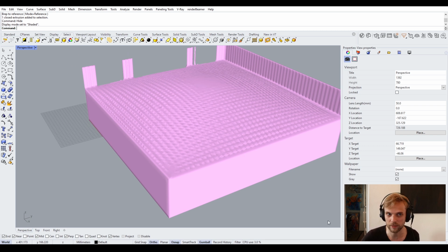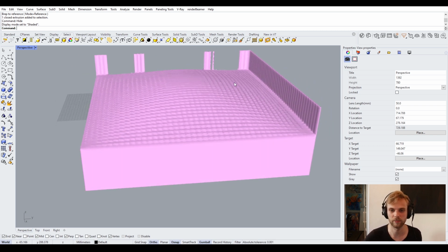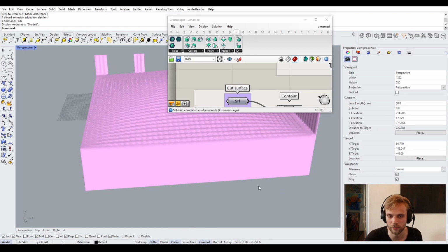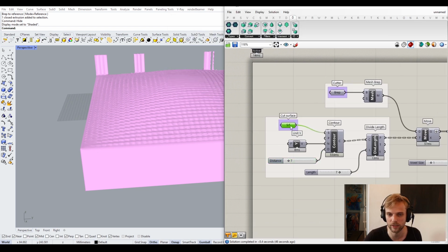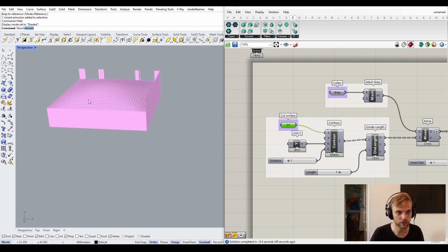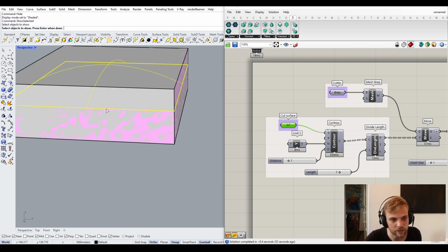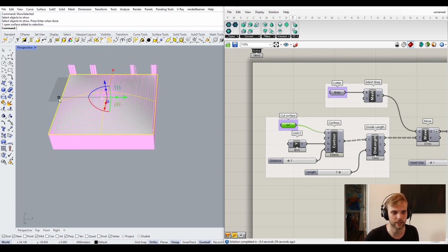So that's the basics of it, right? By the way, you remove this by just shrinking the box a bit before the simulation starts. As easy as that. Or enlarging the box before you create the cut surface. So actually, let me do that. Show selected. Where's that surface? There it is. That surface, if I just scale it up 1.01, like if I scale it up 1%, or let's do 2%, 1.02 in all directions.